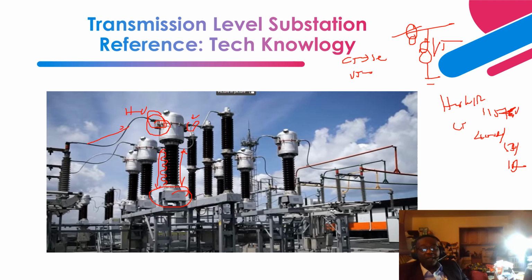If you have industrial facilities or any other pollution facility that is emitting a lot of pollutants, these pollutants will fall on this surface, and periodically it's going to build up contamination, and leakage current will start flowing. So the way it is shaped is to stretch and increase the creepage distance. Inside this enclosure, it's oil filled with the winding and the core.